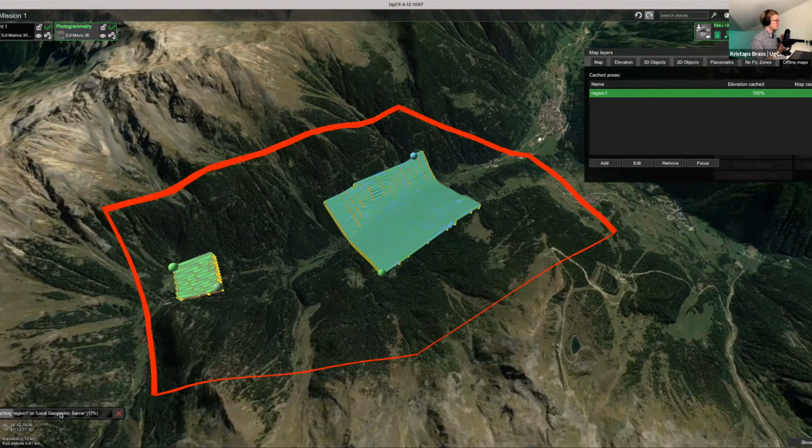Plus, one thing is that obstacle detection systems, depending on what kind of sensors are used, also are not 100% reliable. So nothing is 100% in life, of course. But yeah, so in general, rely on your own pilot skills, rely on the fact that you know where the drone is going to be flying, what things might there be in the way. And yeah, then of course you still have the obstacle detection systems just in case.